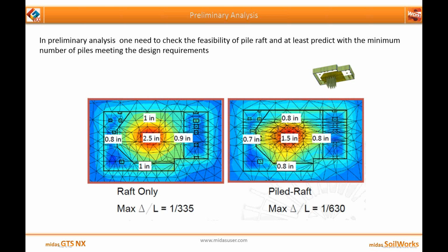So what we do is that we create a model, we consider only raft and, let's say, pile raft, and then we check for the maximum displacement and the maximum differential settlement which is occurring in the pile, and thus we can decide whether one should go for raft only or whether one should go for pile raft. So this is basically the analysis which we'll be performing today in our case study.